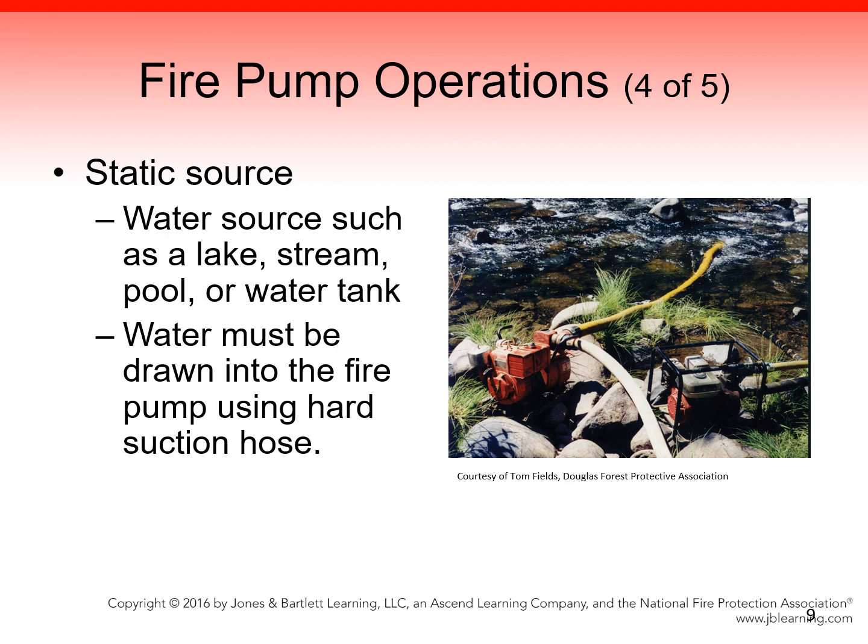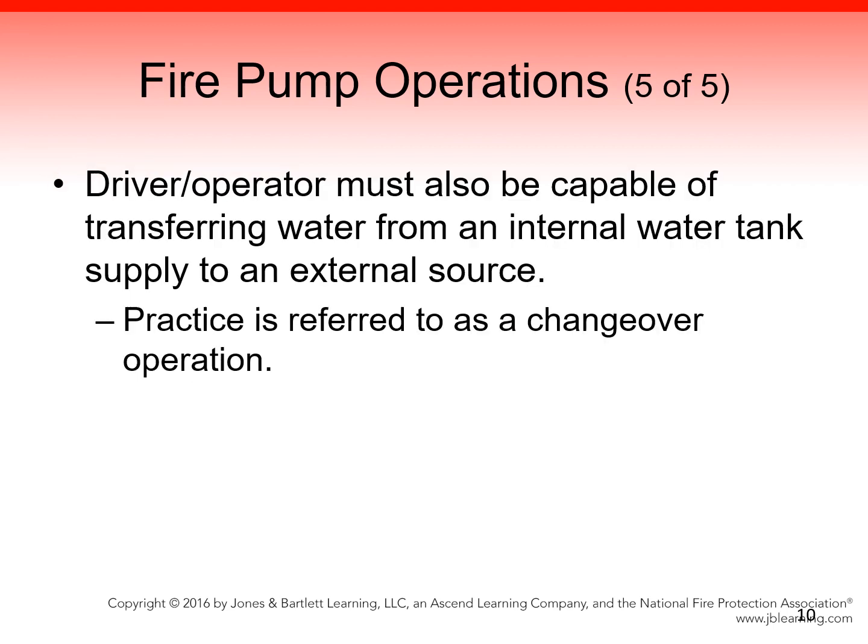Water must be drawn into the fire pump using hard suction hose. This operation is covered in the chapter Drafting and Water Shuttle Operations. The driver-operator must also be capable of transferring water from an internal water tank supply to an external source, a practice referred to as a changeover operation.